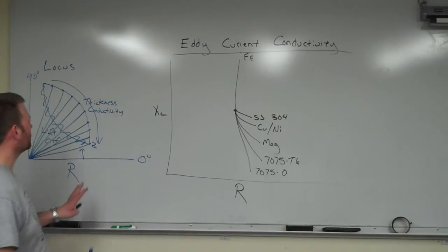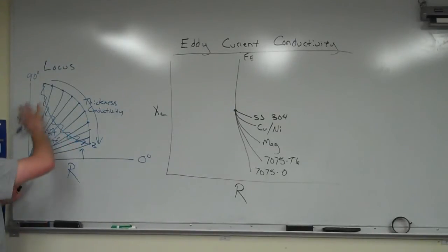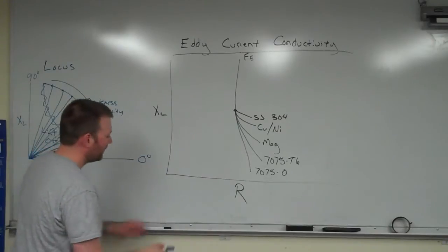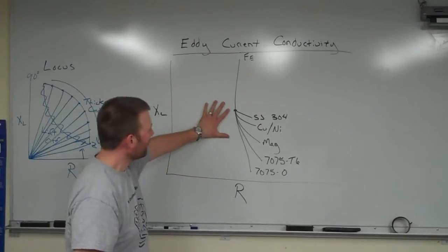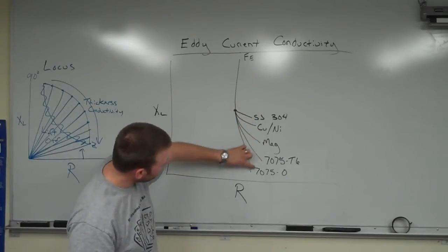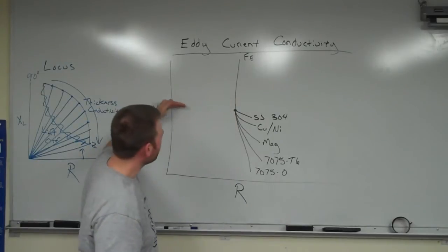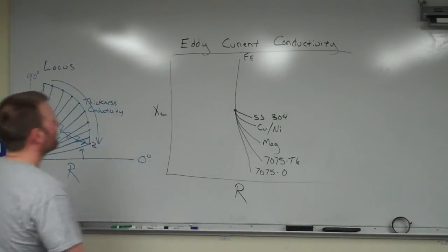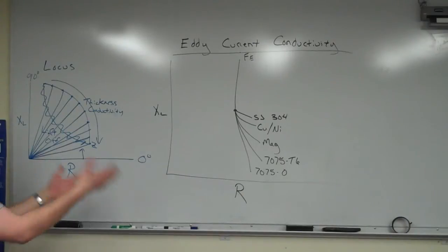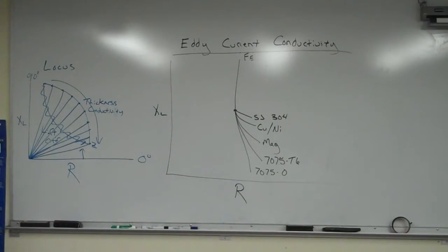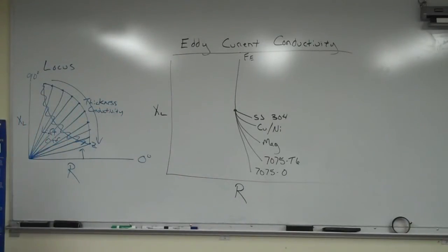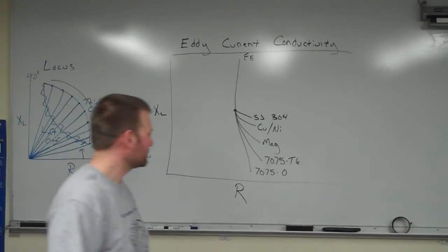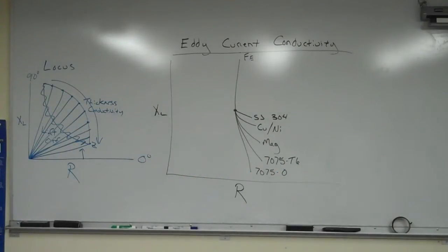Now, what we're more concerned with for now is just our conductivity lines and how this is all going to play into measuring the thickness of a piece or measuring different materials. So, basic conductivity curve: increasing conductivity as we come down here, and ferrite or anything that's magnetic is falling up here, which is how I orient my screens. You don't have to orient yours that way, but it's easier for me to understand because inductive reactance and resistance all go up. If it's magnetic, everything comes down; if it's non-magnetic, it's just easier for me that way. So that gives you a little shot of what's going on there.